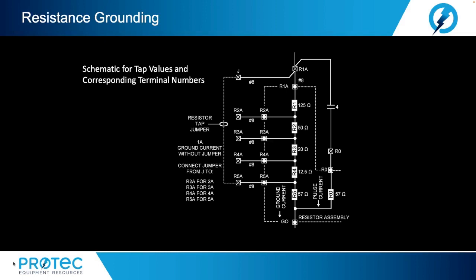The reason for choosing a grounding resistor value lower than the capacitive coupling is so that in case of a ground fault, the return path of the ground current will flow through the grounding resistor and not through the alternate capacitive path. Note, for most systems, a resistor tap setting of 5 amps will exceed the capacitive charging current of the system, yet still prevent equipment damage.